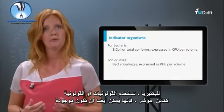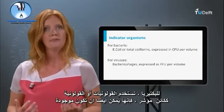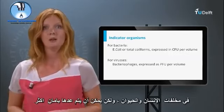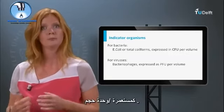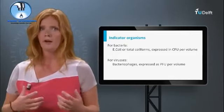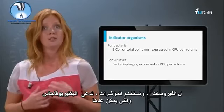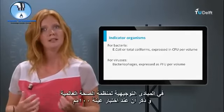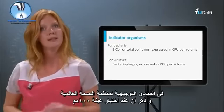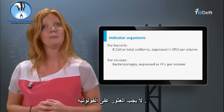For bacteria, coliforms or E. coli are used as indicator organisms. They can also be found in human and animal feces, but can be more safely cultured and counted as colony-forming units per volume. For viruses, indicators called bacteriophages are used, which can be counted as plaque-forming units per volume. In the guideline of the World Health Organization, it is stated that when testing a 100 milliliter sample, no E. coli may be found.